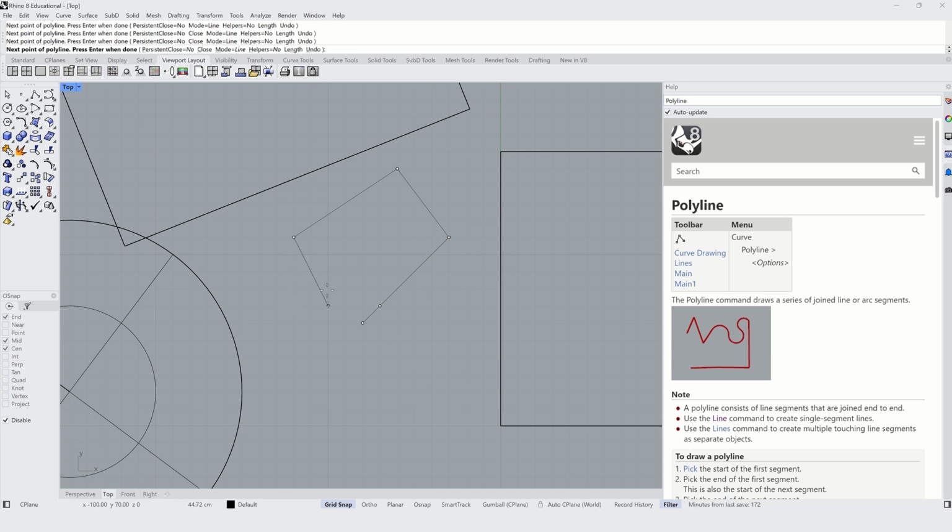I usually leave this off. That limit feels overly restrictive to me, although sometimes it does have its benefits. And when I click it off, you can see that now I'm able to choose points that are in the middle of squares. The option next to it is Ortho, and you can see that this will immediately lock your